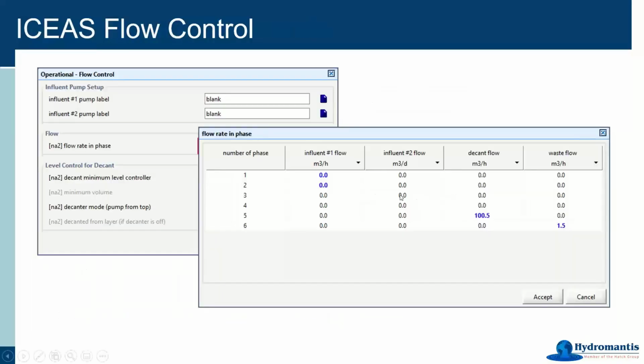First of all, we are going to set all of the influent flow to 0. The reason for this is that we're not actually specifying for the flow to come in at a specific time, because it is going to be coming in all of the time. We are not actually going to control that flow coming in. It is going to be dictated to the SBR unit by what's going on in that immediately upstream CSTR.